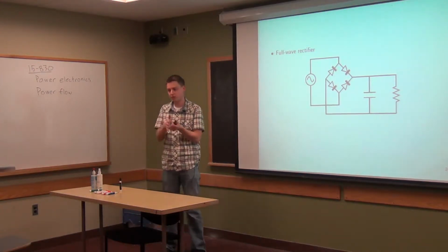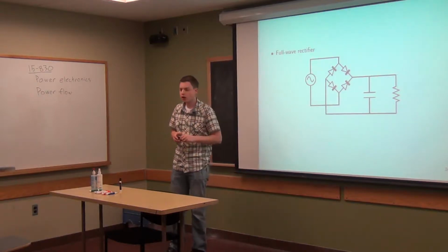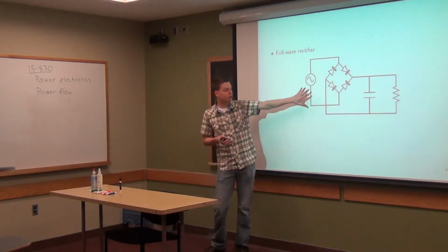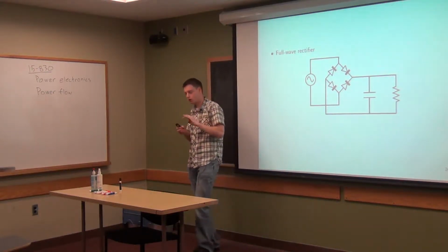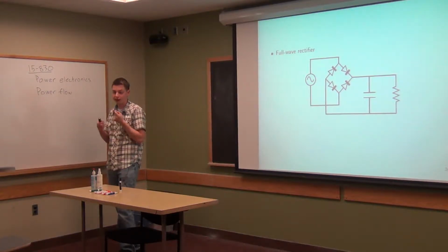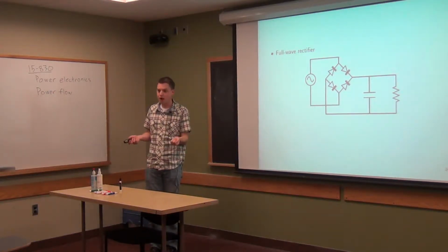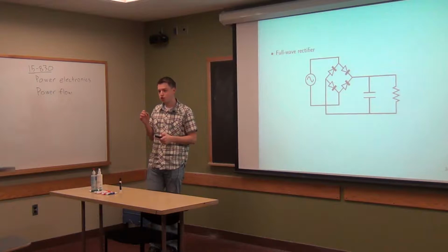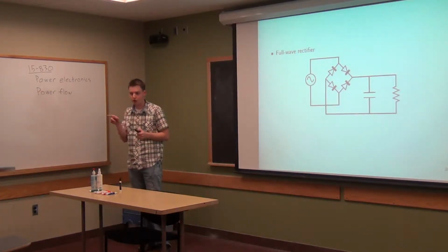So if you want to detect what kind of devices are on in a home, for example, which is something that I've done a fair amount of work in, it can really help to know exactly how these nonlinear circuit elements are going to distort the current signals. You can actually use that as a signal of what kind of devices are on, right? So if a light bulb and a monitor use the same amount of power in total wattage, you could still tell which was which if you were actually able to look at the actual AC waveforms, because the monitor would